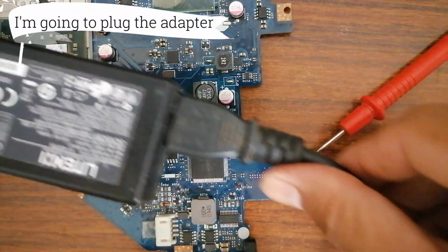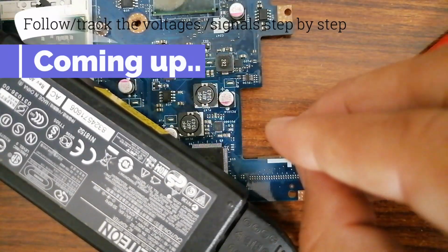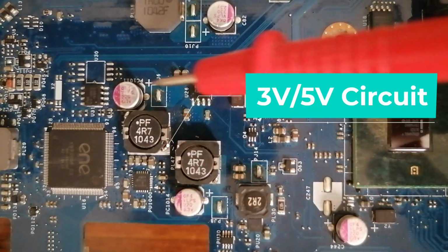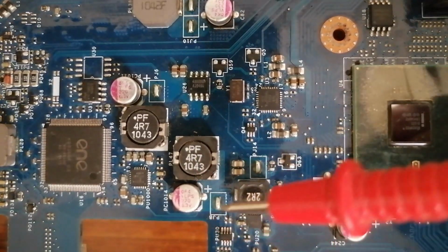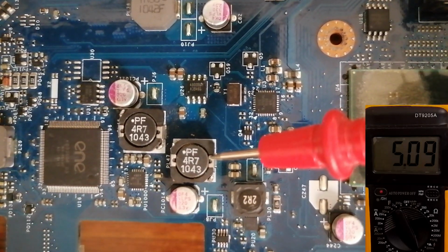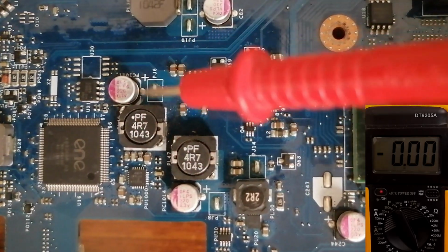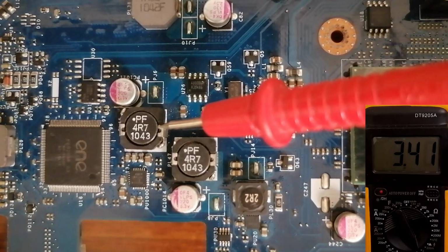I'm going to plug the adapter to the motherboard and then follow the voltages step by step. This circuit is the 3 volt 5 volt circuit. Here we have the 5 volt channel. If we check this inductor, we have 5 volt in the multimeter, and this is the 3.3 volt channel. This inductor, we're going to find 3.3 volt.